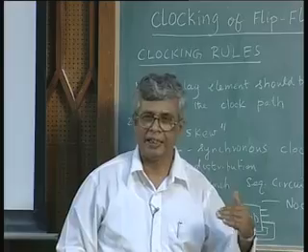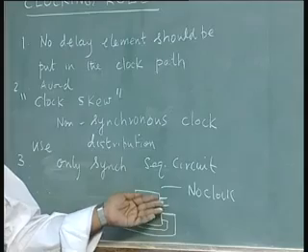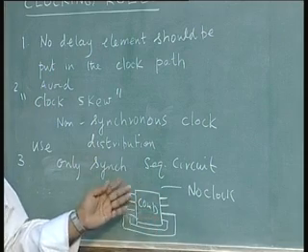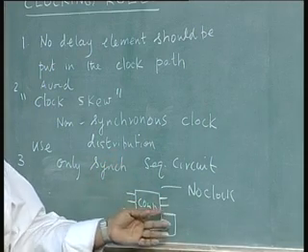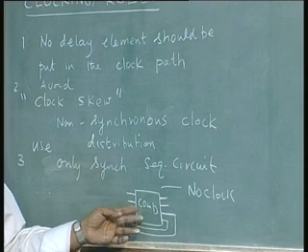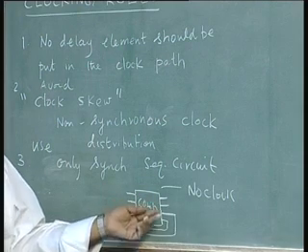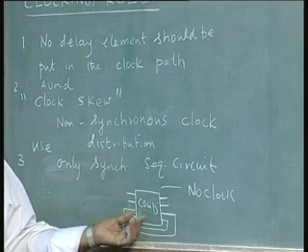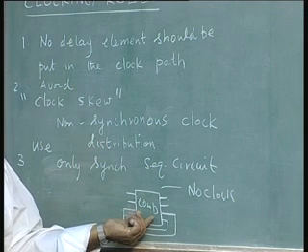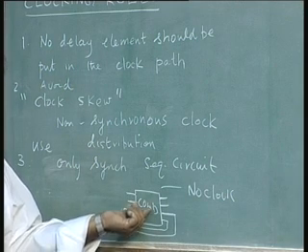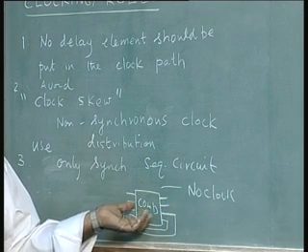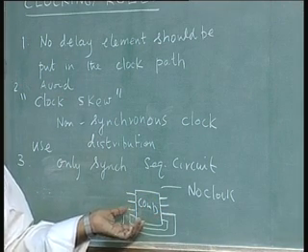A sequential circuit is a circuit in which outputs are determined by the present inputs and the previous outputs. The previous output is fed back into the gates, which will again affect the present state. So this goes on. Now there is no control when these things will happen. It all depends on the path delays, the delay path of the combinational logic inside, that will determine.